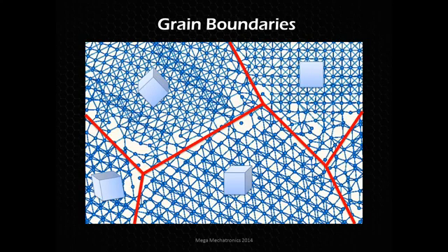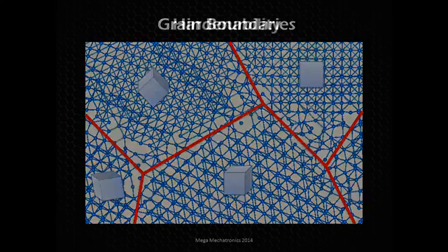The size of the grain is definitely important. If you have smaller grains, more of them, that's going to give us a stronger, harder material, because we're reducing the ability for that crystal lattice to deform and move around, since the grain boundaries are sort of like a wall stopping them from moving any further. On the other side, if we have huge grains, that makes the material more ductile, because we're allowing those cubic structures to move around, deform, reorient themselves and shift around.